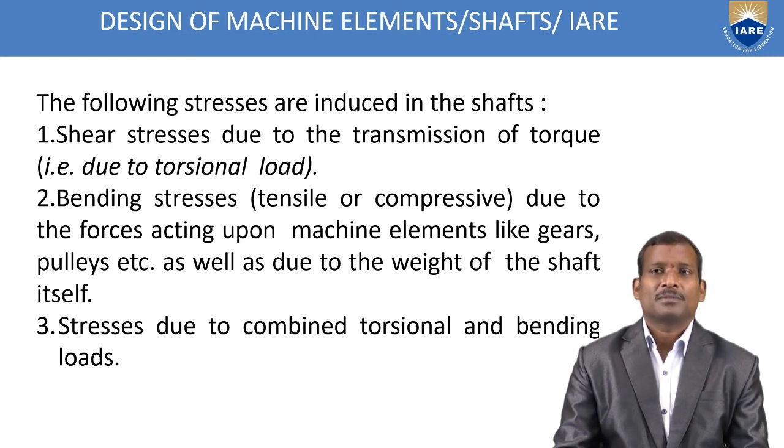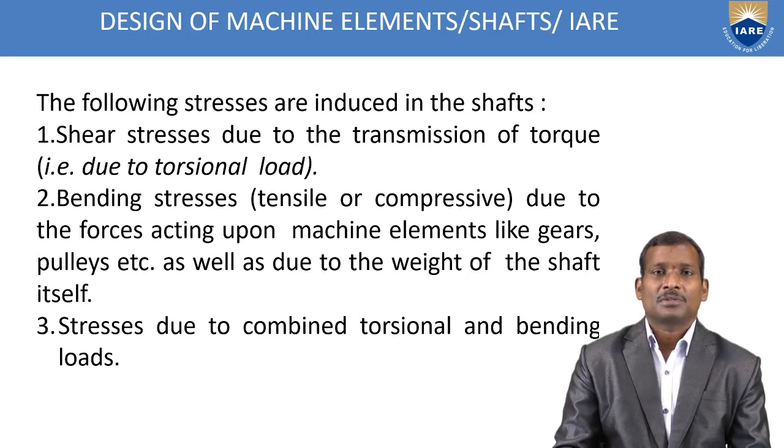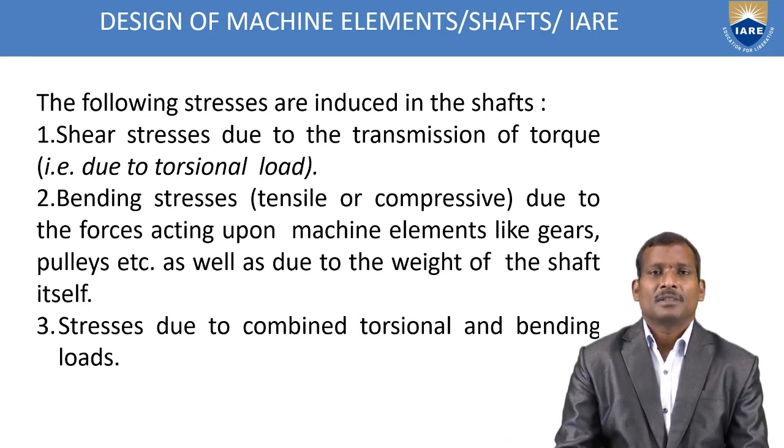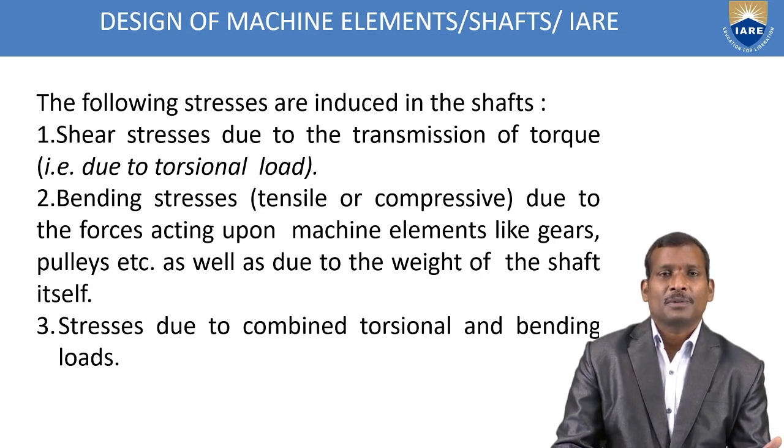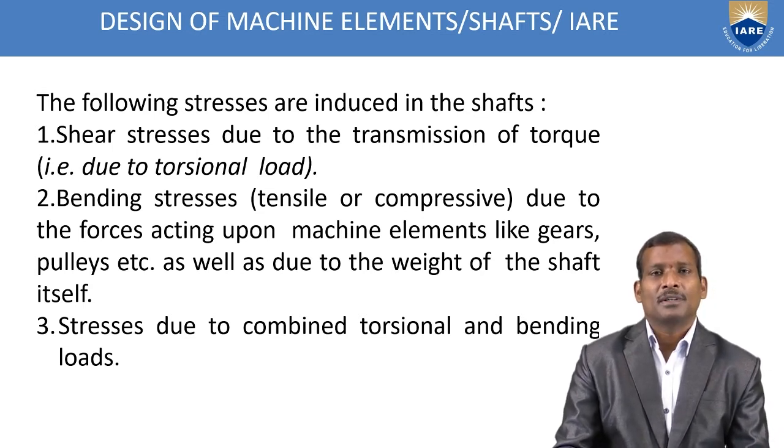Similarly, bending loads, and a combination of these two. Sometimes due to the self-weight of the machine elements, some bending moment also will occur in the shaft. So that's why, in the design of the shaft, you should calculate all these forces and stresses.